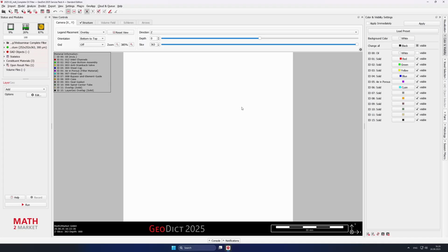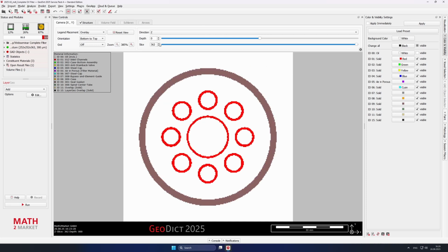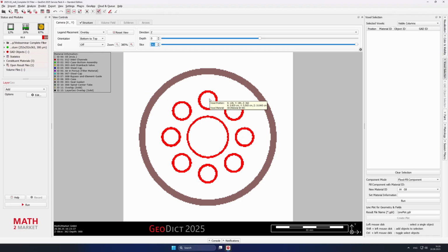We should get rid of it, but I will definitely also show you what happens if you do not get rid of it. And how to get rid of it is pretty simple. I will show you that afterwards. So first things first, we will assign input, inflow, and outflow. We go to the first actual slice, click on select voxels, hold shift and click on the areas which are the inflow.